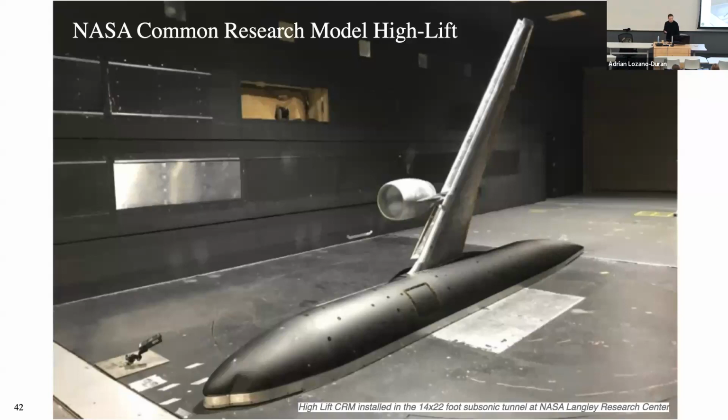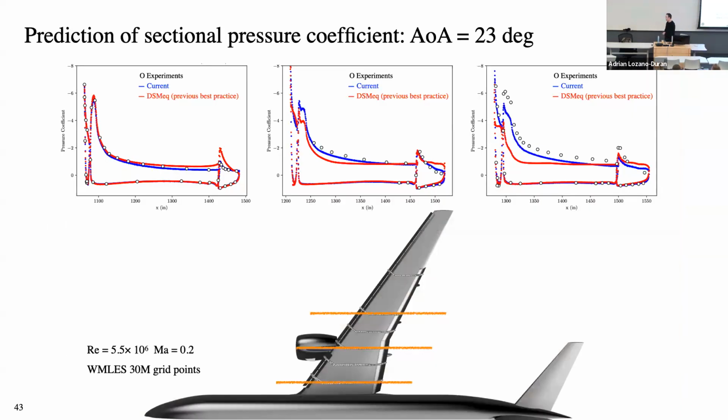And this is an example, just to illustrate this in a way that is more concrete. We run the model now in a case where we don't have such detailed information in space and time. This is the CRM-HL, an aircraft in a high lift configuration. Here I'm showing you some results of the CP at different locations. We have a reference solution that is the best practice from Boeing. For this grid, we use the same grid as the people from Boeing. The blue is our prediction, just to show that it's always pushing the solution, and it happened in this case in the right direction, even if not perfect.